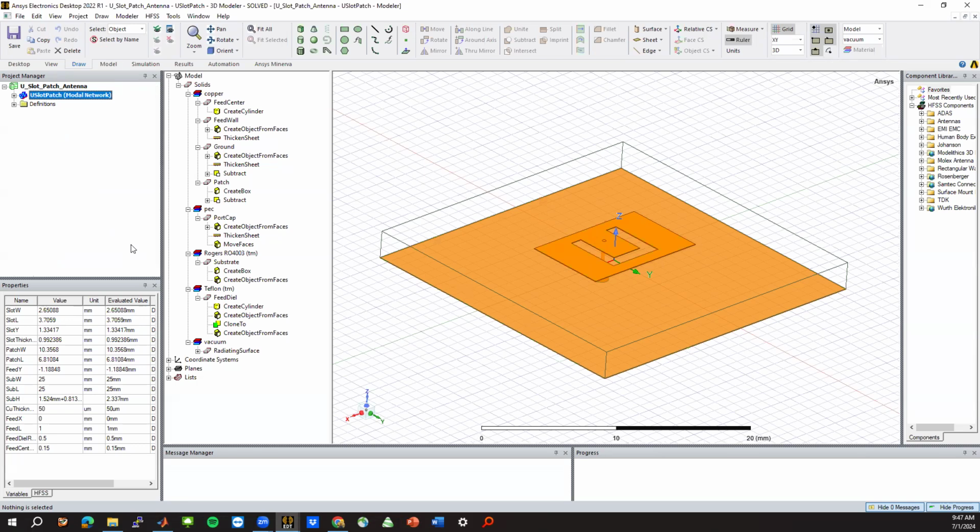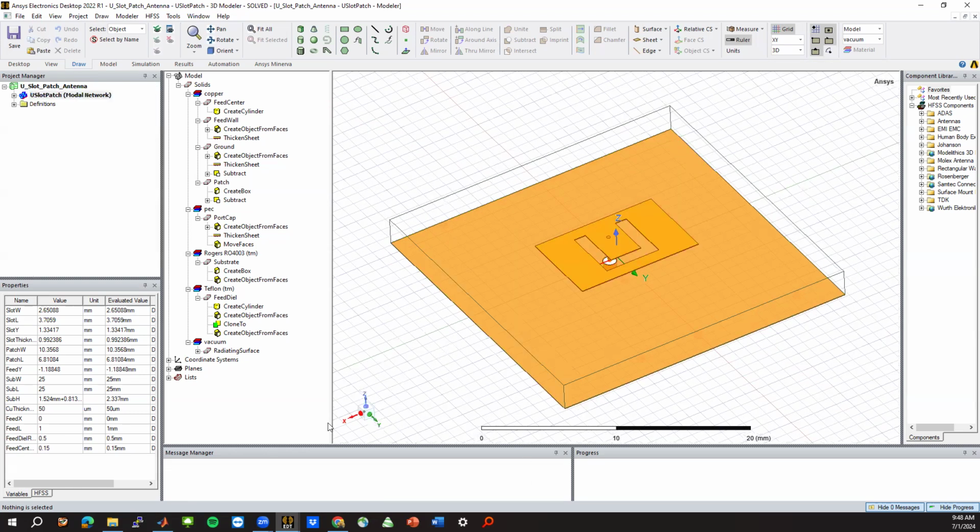So let's say you have some transformer and you want to get a certain matching network out of it, or you want to get some certain S parameters out of it, or a certain coupling and L1, L2 factors from it. What you can do is you can use optimization like what I will show you in this video to do that. Okay, so what we'll use is not the optimization tool inbuilt in HFSS.